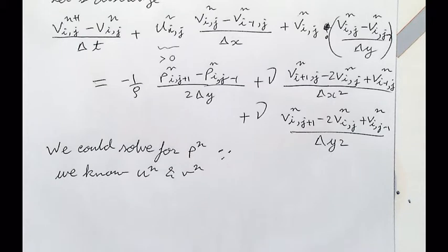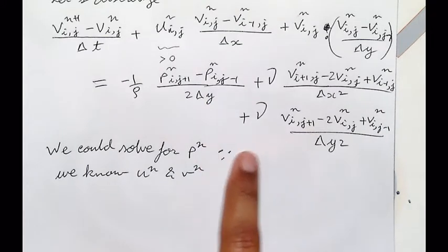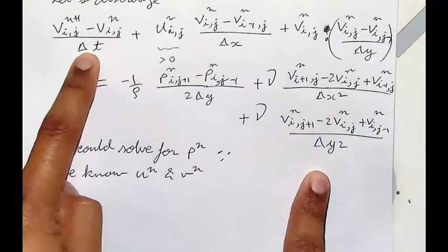Does anybody know what the problem is? Stability. Stability is a problem? Why do you say that? Depending on your grid. So you're talking about the CFL condition and the stability of the diffusion equation that we had derived, the diffusion term. But that's fine. We have done an upwinding here, and we will make sure that the time step we take is small enough that we don't get this instability.